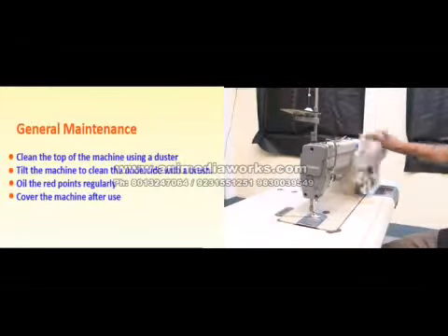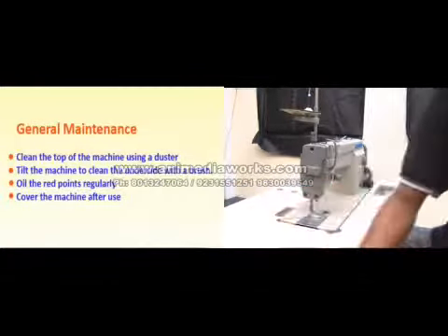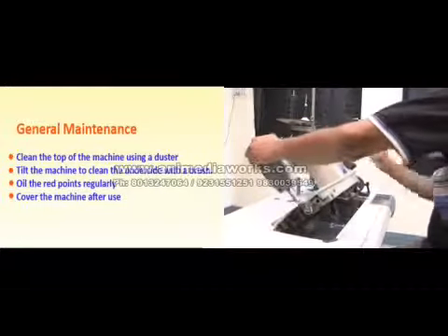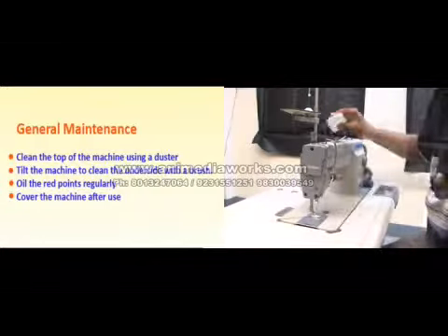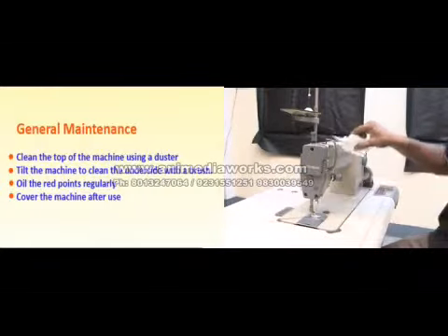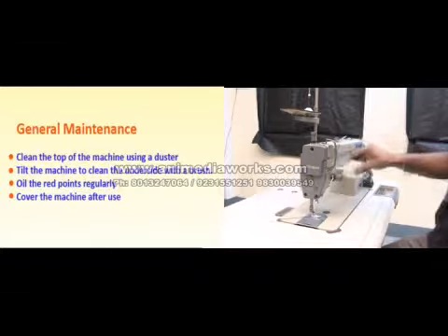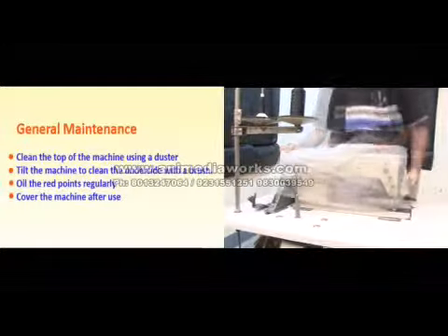General maintenance. Clean the top of the machine using a duster. Tilt the machine to clean the underside with a brush. Oil the red points regularly. Cover the machine after use.